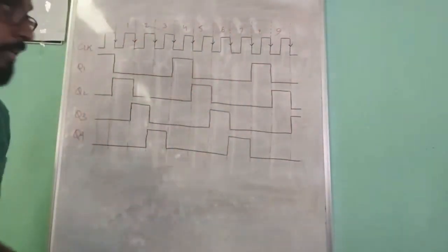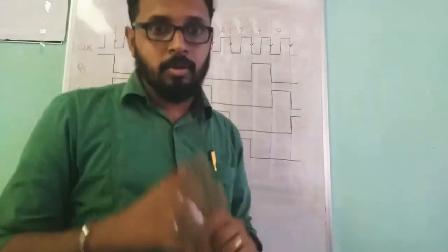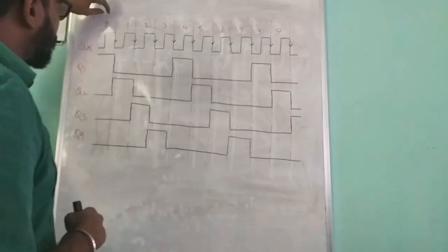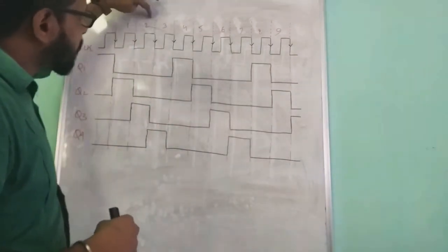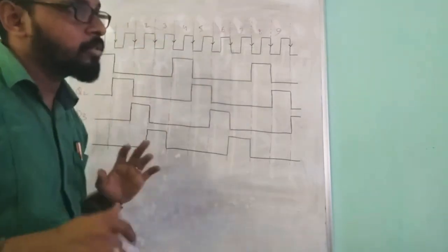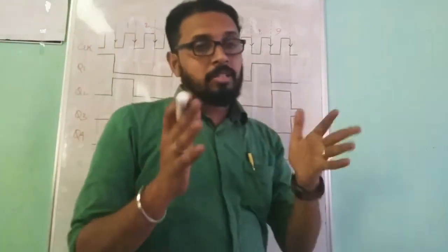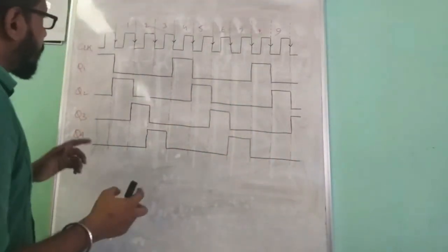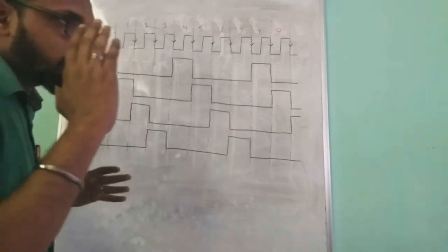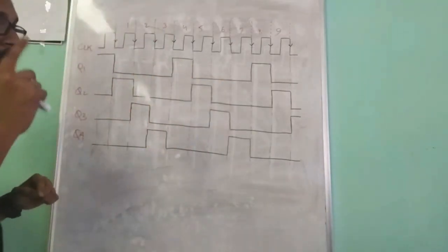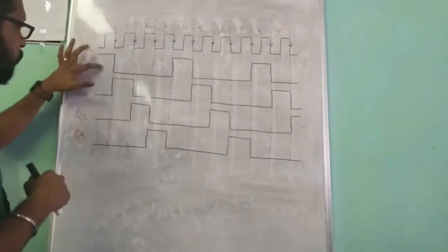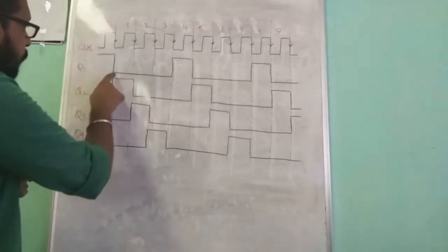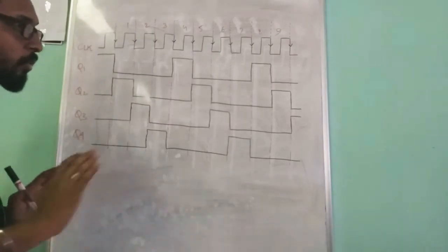This is the timing diagram of a ring counter. How can we draw this diagram? In textbooks you may not find these values here. So the best thing you need to do is, based on the sequence table that we have just discussed, look at clock pulse 0. There Q1 was 1, so it goes high, and the rest of the values are low.